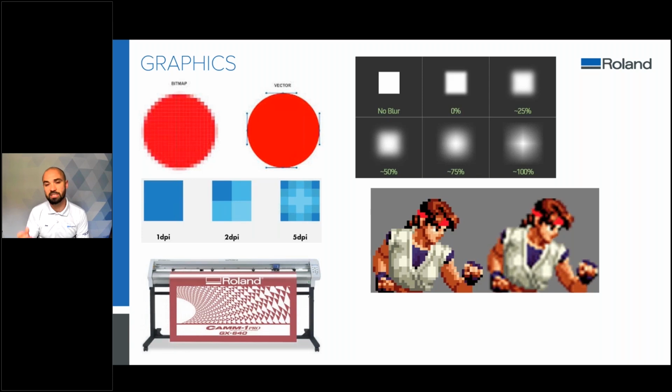And what it basically does is add pixels across pixel boundaries. So it softens the image. As you can see, it's not a better quality image. It just looks softer where you don't see those harsh pixel edges. So you can add interpolation to images in VersaWorks or in your design software to soften them a bit as well.